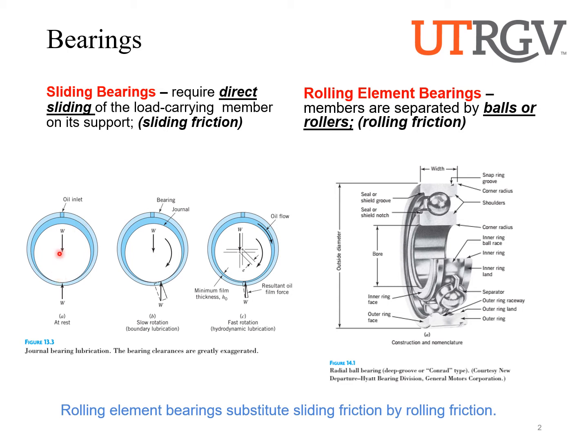And so right now, as the shaft is making contact with the bearing, we can calculate those contact stresses if we so wanted to. But what's important here is that when this shaft starts spinning, you're going to have metal to metal contact, or shaft to bearing contact, until there's enough revolutions on this shaft that moves the oil around. And so eventually what will happen is the shaft is going to be riding on a very thin film of oil, and they're no longer going to be touching each other, which means there's going to be very minimal wear once this has started going.